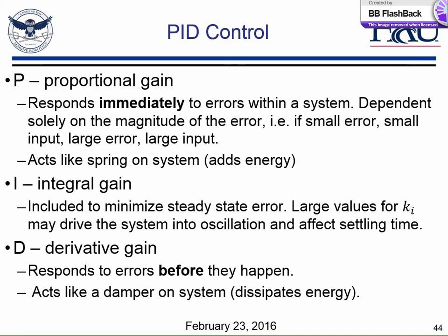With that single gain, you actually see where your poles are for your open loop system. And it's interesting that it's only about 60 years ago that we proved that your poles, as your gain increases, are driven to the zeros in your system. So a root locus plot is a diagram with the poles, and it has a trajectory of where your poles will be as you increase that gain. As k goes to infinity, they will either go to negative infinity or positive infinity, or they'll hit a zero, right? With that, you can set what your closed loop poles will be.